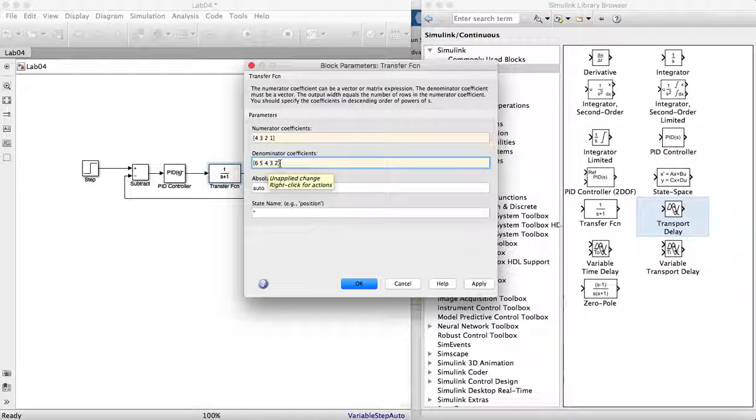But similar to our PID controller, it is desirable to simplify our transfer function in terms of variables. So we just define, because we know that the first order plus dead time transfer function is something like G(s) equal to K divided by tau s plus 1, multiplied by e to the minus theta s, which defines the dead time.